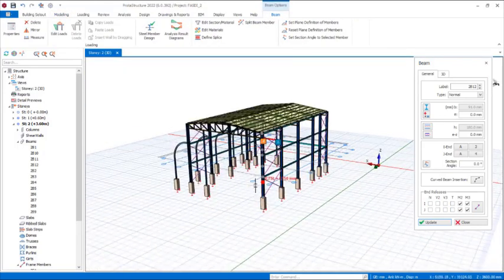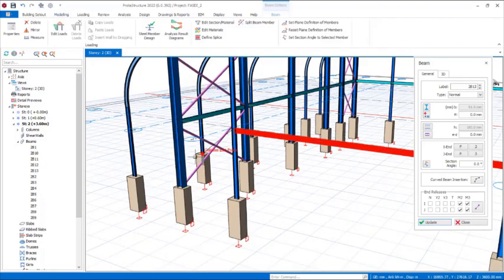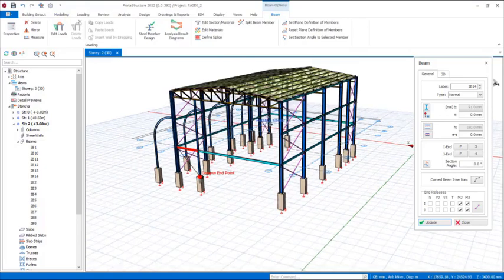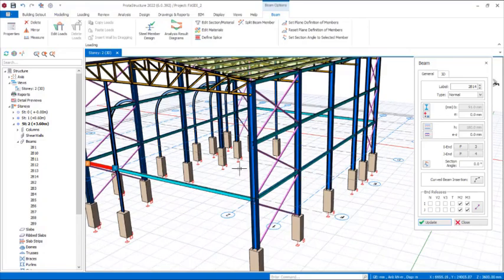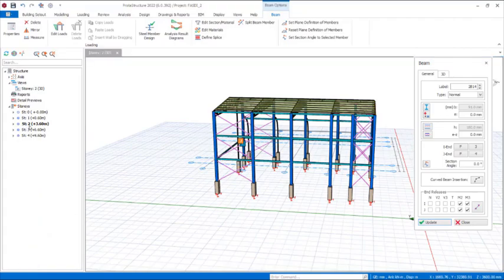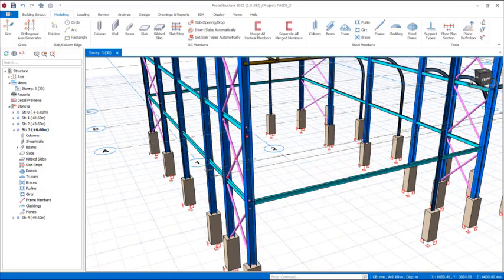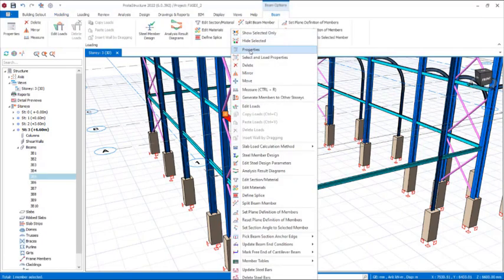All right, so come over here, we'll be having the same thing over here. So you have a beam just like this at that level. So we will be moving the grid lines to the level story 3. So double click right there at story 3. You have this, so select this. We'll be using that property as well.